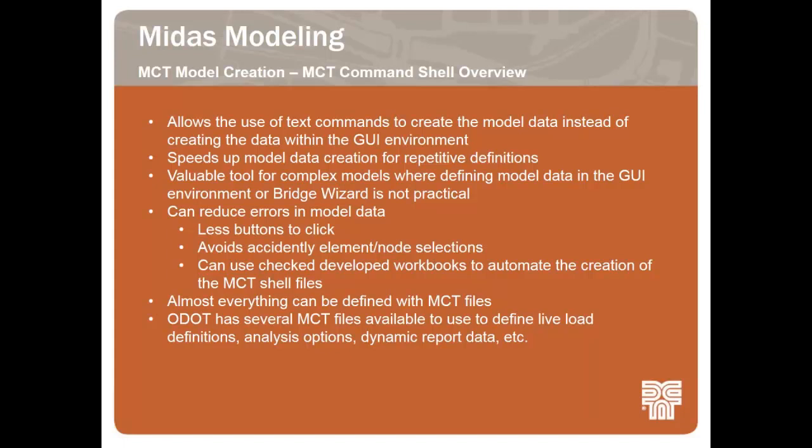So instead of having to manually click and define each item individually, or even using the bridge wizard option, you can use a spreadsheet and macro to streamline the process and be able to do repetitive commands for a single bridge or for multiple bridges.